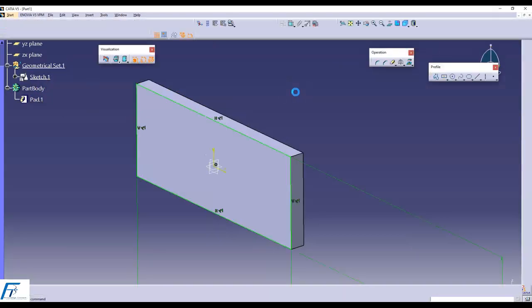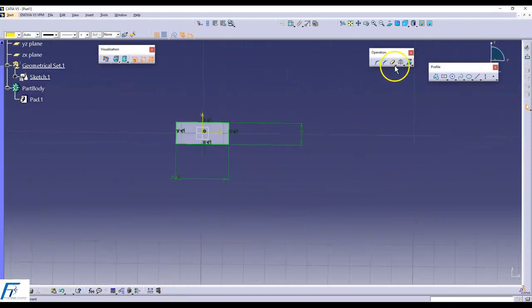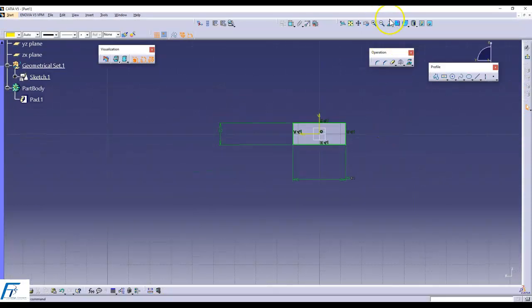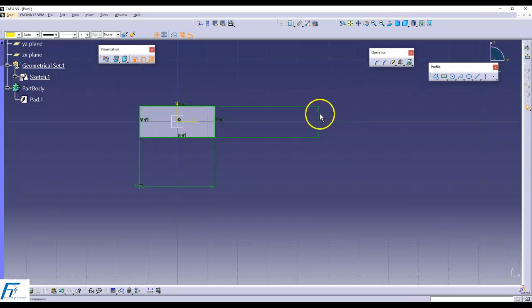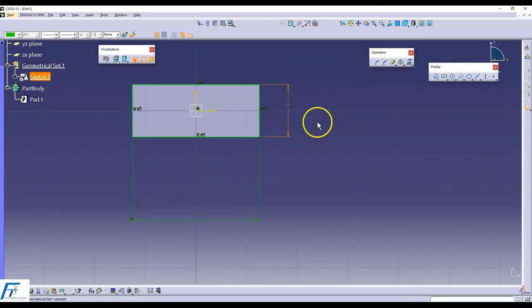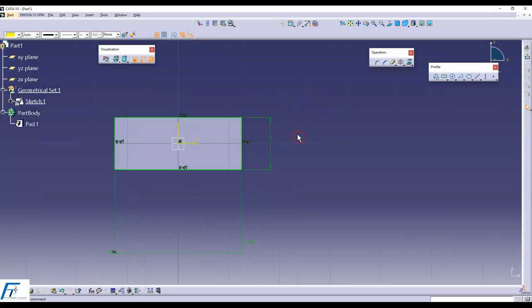Just go do it, and this is what we in the industry call configuration management. What is that called? Configuration management. Why do we need configuration? I can't create any n number of components at the same time, right? I just do only one, give relation, and I can have like this 10, 12, 15, 16, 17, 18, from different dimensions. I can have any number of dimensions, right? In this case, only 10 is there. I would like to have 12, I would like to have 14, I would like to have 16 width. So I will get different configurations.